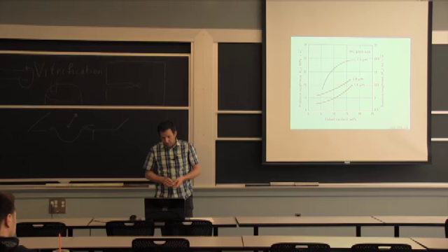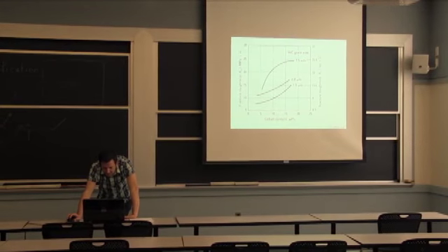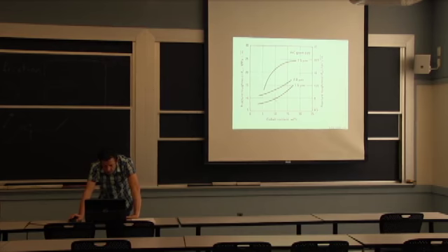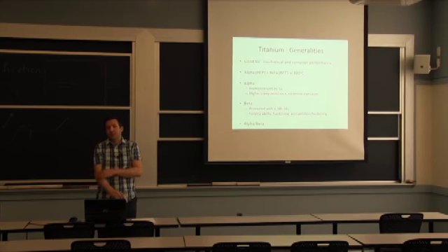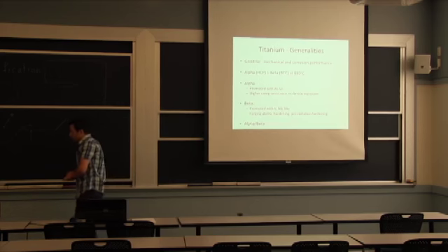So you see the effect of grain size and the binder content. So you reach a point, and 10% cobalt is not uncommon for a cemented tungsten carbide. It gives you a fracture toughness either below or above 15, depending on your grain size and grain size distribution as well. So it's really something to keep in mind when you're trying to put together an assembly. If you're going to have parts that are going to be contacting each other, we haven't talked a whole lot about wear, but